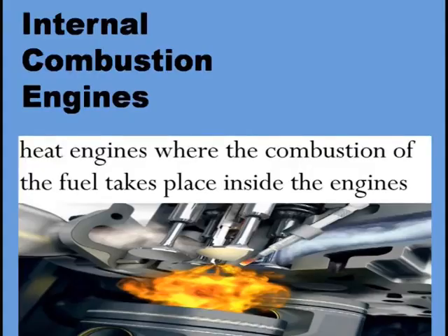Here, if it is a petrol engine, inside this cylinder, in one process of suction, we have supplied air plus fuel vapors into the cylinder. If it is petrol, air plus petrol vapors are available inside the cylinder during suction. If it is a natural gas engine, then an air plus natural gas mixture is available inside the cylinder during suction, and that air plus fuel mixture we are compressing.